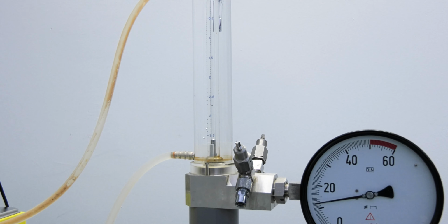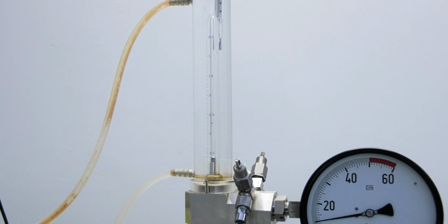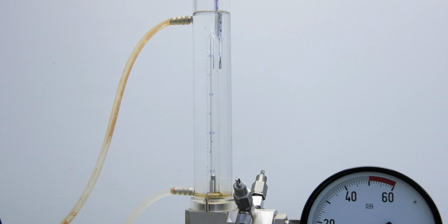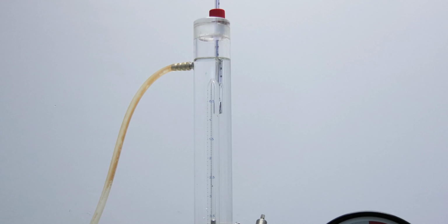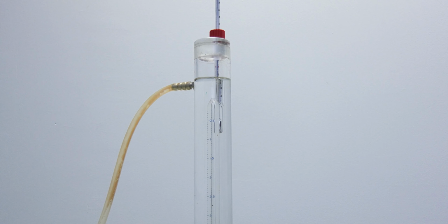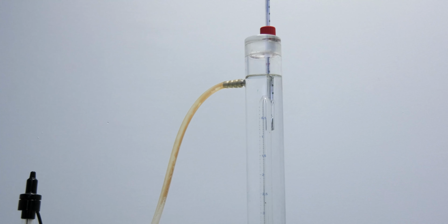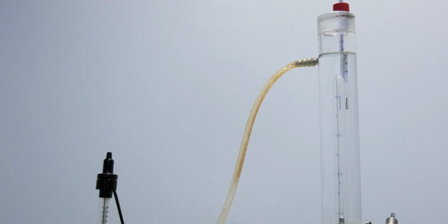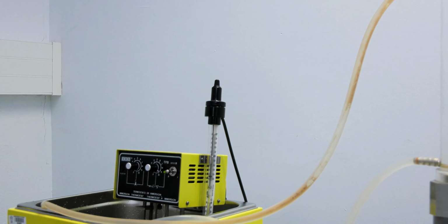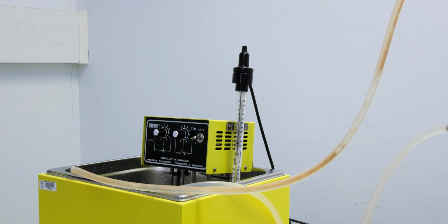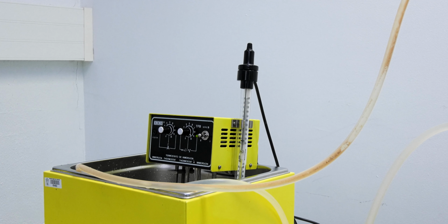The temperature of the fluid is measured indirectly. The tube that contains the fluid is surrounded by another concentric tube. The annular space is filled with water proceeding from a thermostatic bath. When a steady equilibrium between the static fluid and the water is reached, the temperatures of both fluids are the same. Then, it is only necessary to measure the temperature in the water. With this apparatus, we will measure temperatures in the range from 20 to 50 degrees Celsius.